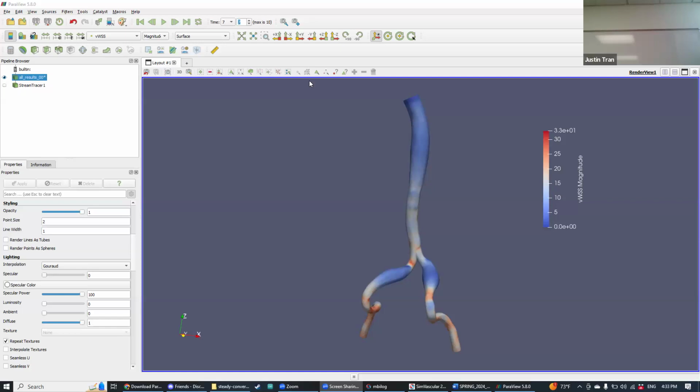The first one is called prescribed velocity. That one you're going to put for your units. And then for your outlet, you're going to change all of them to the second option, which is resistance. So it'll just be one inlet. Well, for you, you're going to have two inlets. So you actually do maximize your velocity. This is one inlet right here, and this is the other. So you're going to have flow coming from both sides.